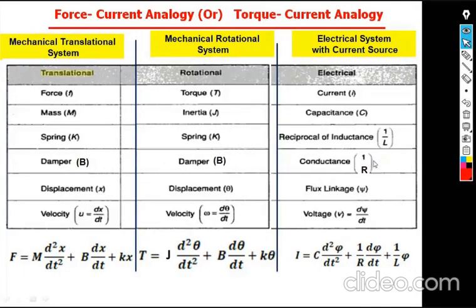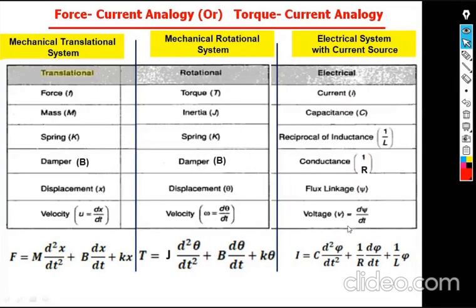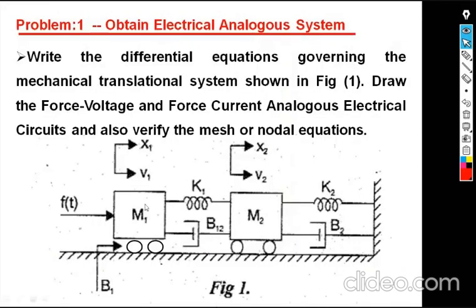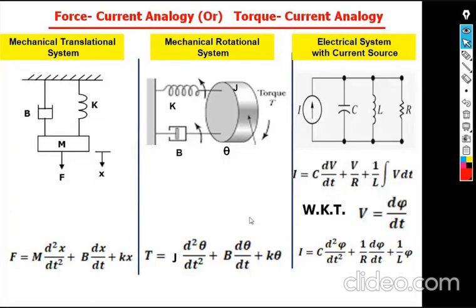So like this is by comparing equivalents, and all of you must remember that here, x is equal to charge and velocity or angular velocity is equal to current. Now here x is equal to flux and velocity or angular velocity is equal to the voltage. After writing the equations in this form, completely redraw the electrical circuit for the given mechanical system, that is enough.